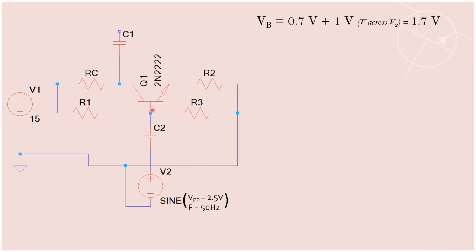For this transistor to turn on, we have to have an approximate base voltage of 0.7 volts with respect to the emitter. But in this case, we have 1 volt on our emitter. Remember, VR2 is 1 volt, and that is the voltage across R2. So we have 1 volt on our emitter. It means that if we have just 0.7 volts here to ground, emitter voltage will be higher than the base voltage, and so we can't have this transistor turn on.